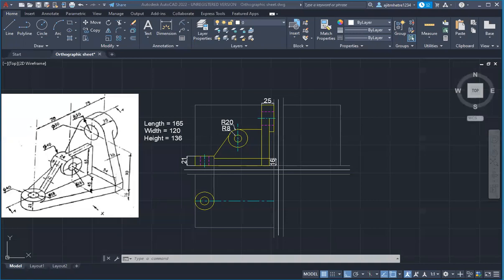Yes, I got many hands raised, I think so. Only one. Yes, Jihan, go on. Sir, do we have to draw the projection line, or have you shown it only for reference? No, you have to draw. You have to draw. Straight line or dotted lines? No, light line. Straight line, light. Continuous line, but it should be light line. Exact, it should be very light.